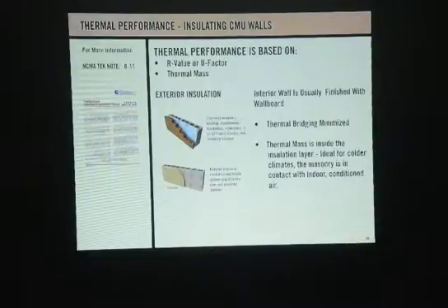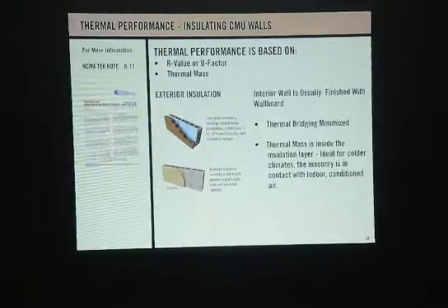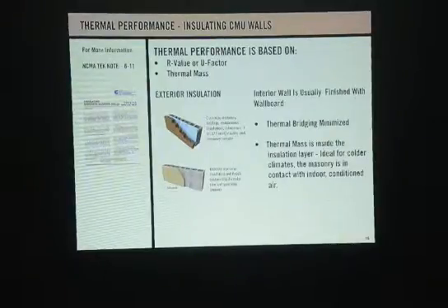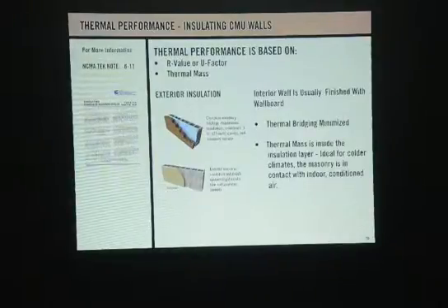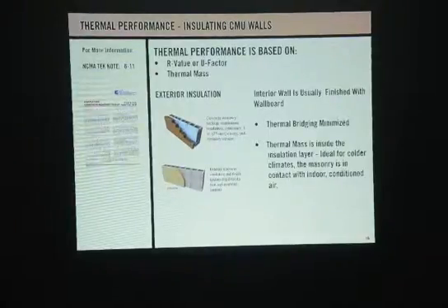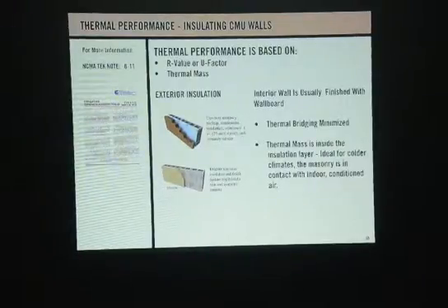But mold and mildew is an important problem with condensation, and it's something that we don't always think about. The good news is, if we go pre-insulated block, stucco doesn't have organic material, right? Correct, compared to drywall. With stucco, you don't have that problem. So for a frame building, you're in good shape there. But sometimes, if the building is not properly insulated, that's where the conditions change, and we have potential for issues. We're just about done, gang.